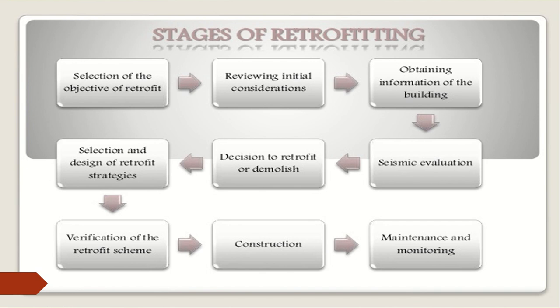Then reviewing the initial consideration. What are the considerations you have given? Whether you have considered the loads coming on that, or the seismic activity which is acting on such building, etc. Then we have to obtain the information regarding the building, like the load which is coming on this building, what all impact this building has faced, what deterioration it has gone through, and as a result of the seismic activity, what are the damages the building is suffering, and whether this building has undergone maintenance work, and how.